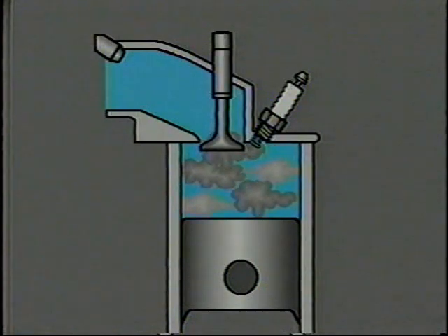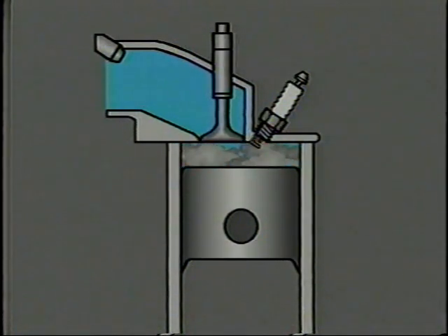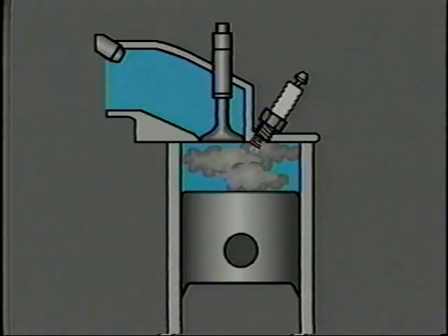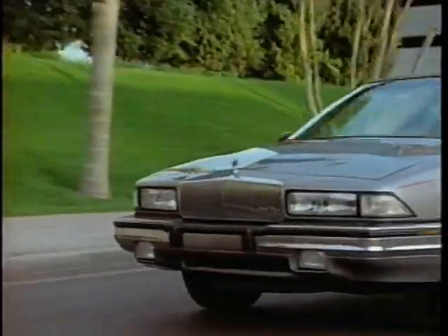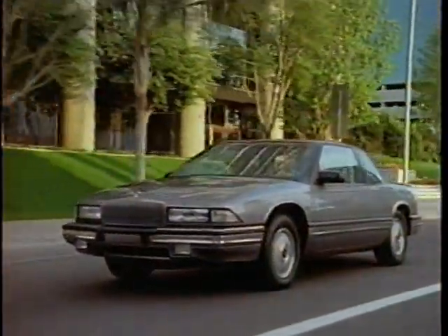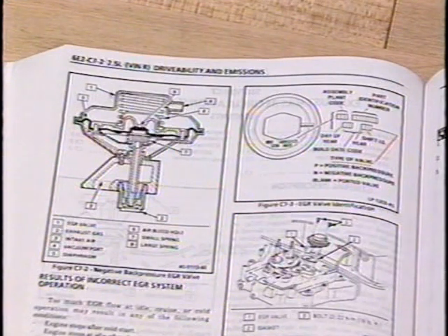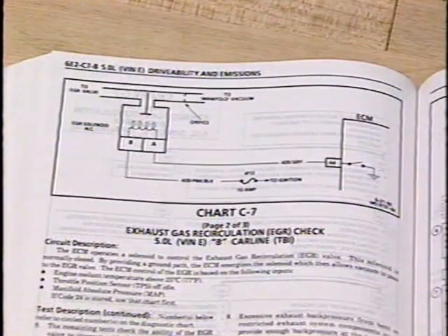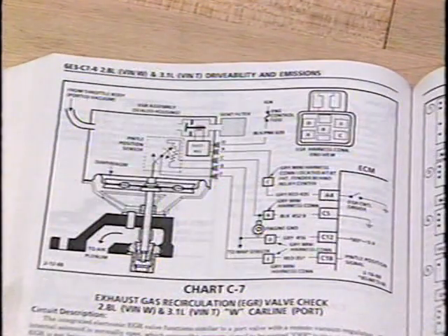If too much exhaust gas flows through the valve and enters the combustion chamber, combustion is poor or does not occur. For this reason, the EGR valve usually only opens when the engine is warm and running at above idle speed. Since 1986, various styles of EGR valves and control systems have been used on Buick engines. Most throttle body systems are of the non-ECM control type, with the exception of the Roadmaster 5.0-liter and 5.7-liter engines. Buick port fuel-injected engines, however, have used three distinct EGR control systems.